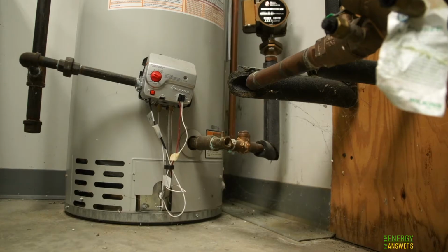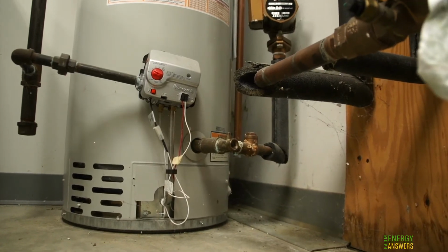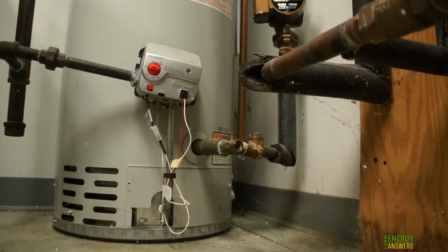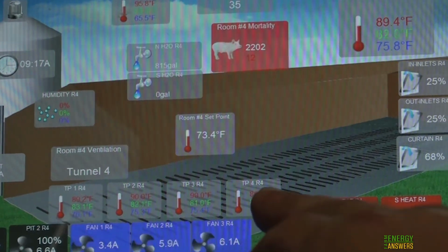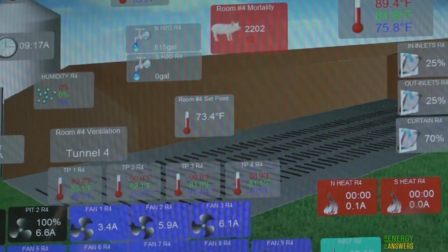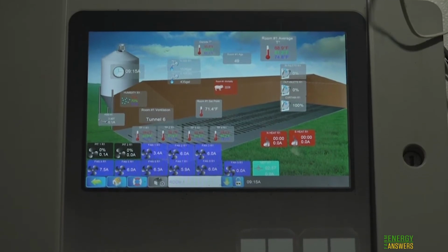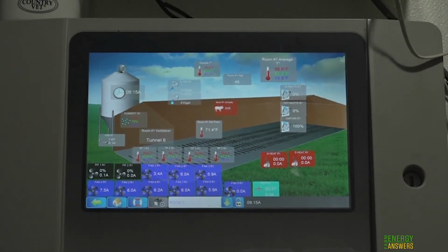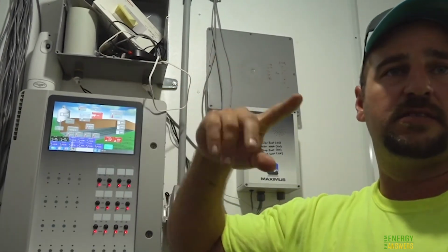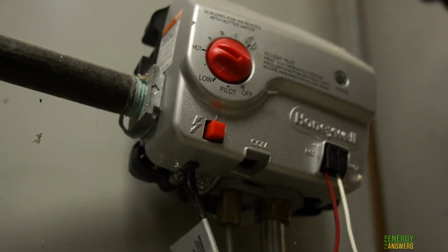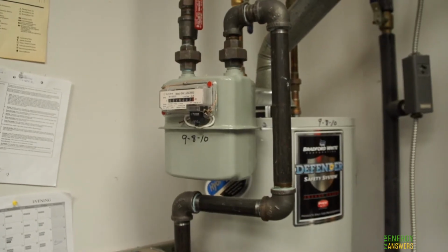A strategy for reducing your energy use quotient is to make sure that devices that have set points are adjusted correctly. Set points are used by equipment to maintain conditions for things like air temperature, water pressure, air vacuum, etc. Those set points are often based on a rule of thumb and may be excessive for your farm. You can often adjust those set points down or install advanced controllers that adjust those set points automatically to provide only what is needed when it is needed. Turning down the thermostat on your hot water heater is a great example of an easy way to control set points.